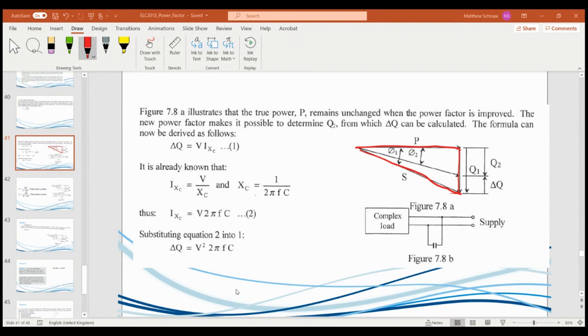Let's say that's a power factor of 0.7, right? What happens now is that we want to obviously increase the 0.7 to maybe 0.85, right? So what we actually do is supply capacitors, as the text says there. So this is the triangle. We actually increase this part here. So we add, this is the capacitor part. So we add capacitors over here.